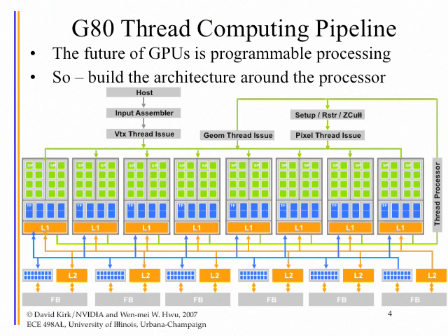The reason why they went this way is so that they can load balance better, because some of the applications require more vertex processing, some applications require more pixel processing. By pooling them together, you can make better use of resources. Okay. However, once you have produced this set, you start to look more and more like general purpose processors.